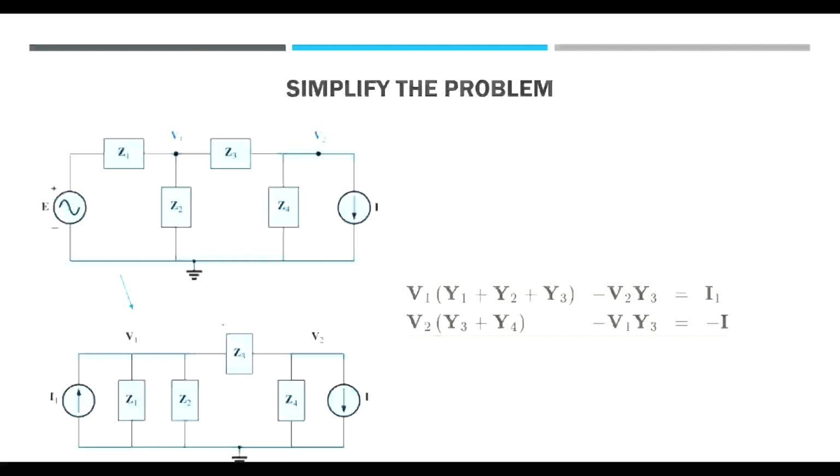Another example would be, if you remember, we can also say that problems where you have a source connected to a load in series can be simplified to the value of V equals IR, where R is Z. So V equals IZ, or I equals V over Z. We have V is E, and Z is given by the value of the resistor or the capacitor or whatever it is, the impedance.